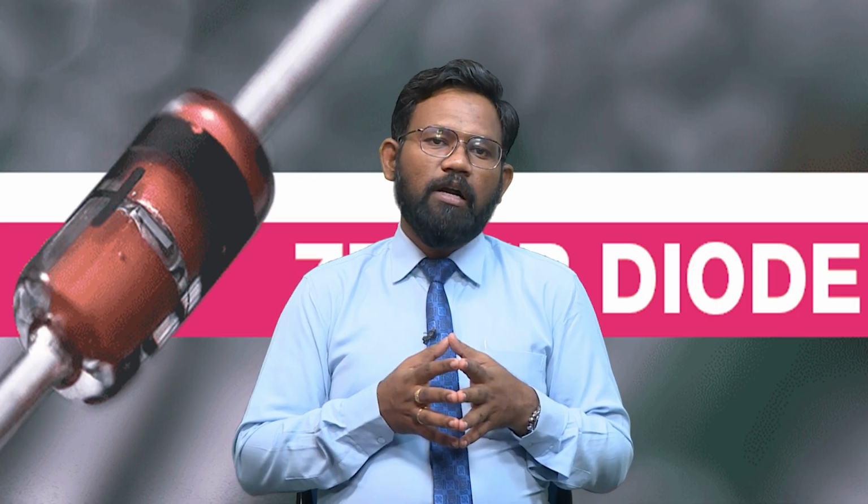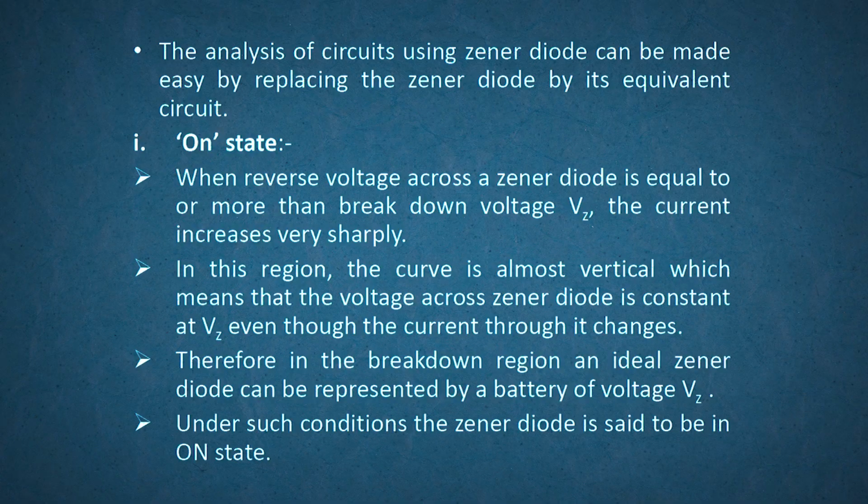The Zener diode works in two states, that is on state and off state. So let us see the on state. When the reverse voltage across a Zener diode is equal to or more than the breakdown voltage Vz, the current increases very sharply. In this region, the curve is almost vertical, which means that the voltage across the Zener diode is constant at Vz even though the current through it changes.